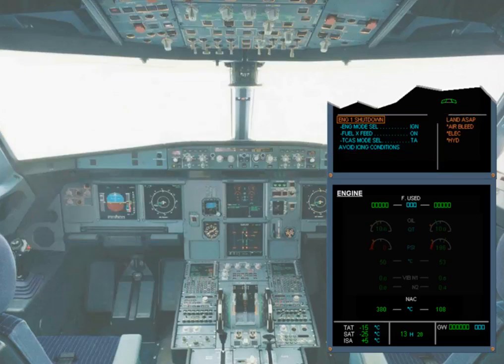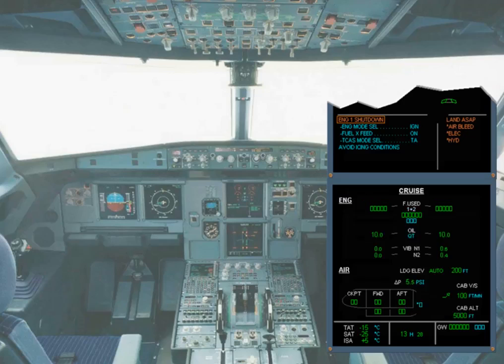The remaining steps are similar to those seen for an Ecam caution. So, we will stop here. You have seen that the Ecam system has provided a smart and interactive procedure to help you to deal with a major problem. Note, as the nacelle temperature is back below the advisory threshold, the engine page is replaced by the cruise page because the caution message displayed on top is not linked to a system page on the SD.